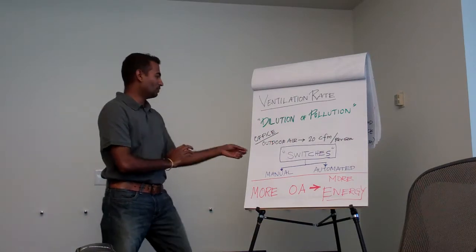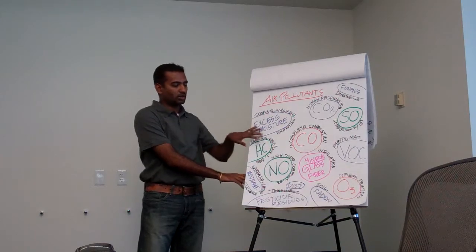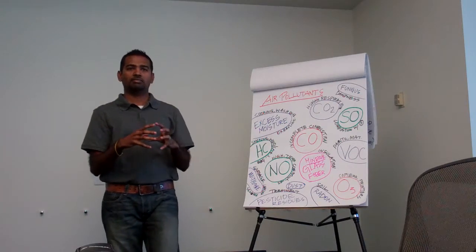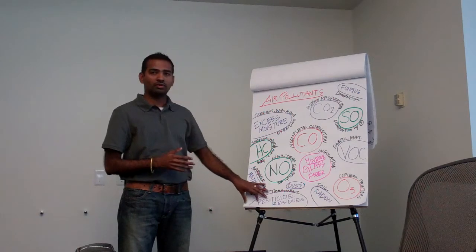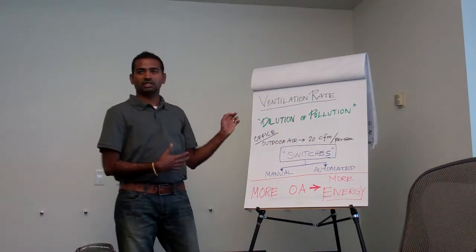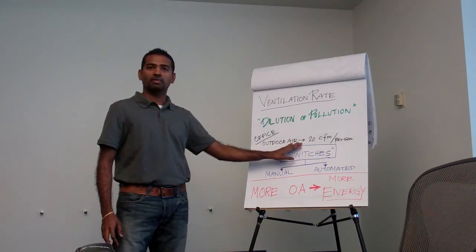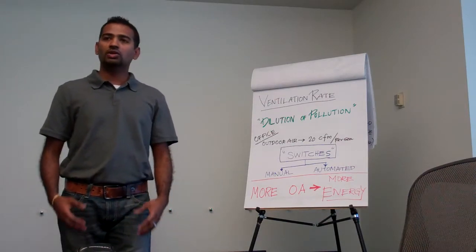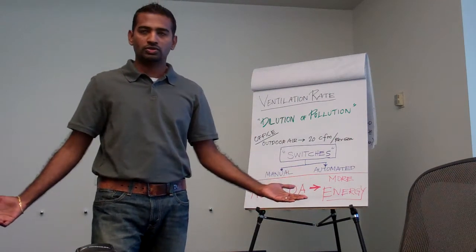So most of these pollutants, some could be completely taken care of by passive design, meaning we properly place and plan these different sources in our planning process. But some we have to rely on dilution. So that's where the ventilation rate comes into play. And for a typical office, outdoor air that we bring in is 20 CFM per person. That includes, correct me if I'm wrong, that includes the sources.